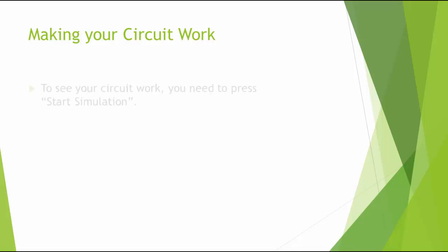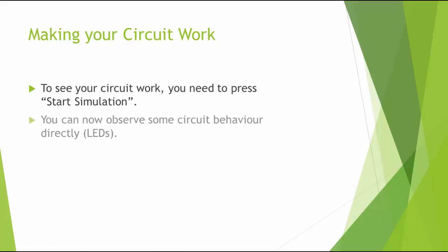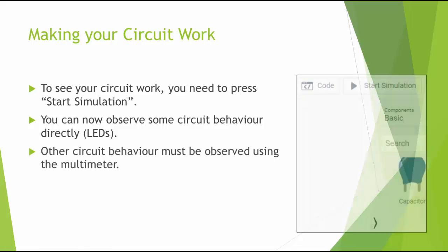Now, once you've built that circuit, you'd expect the LED to light up immediately. In fact, TinkerCAD isn't set up that way. When you want to see the circuit work, you need to press Start Simulation. So there's a button on the right-hand side. When you start the simulation, it's the equivalent of connecting power to your circuit, assuming that you have a power source as part of it. Your simulation will begin.